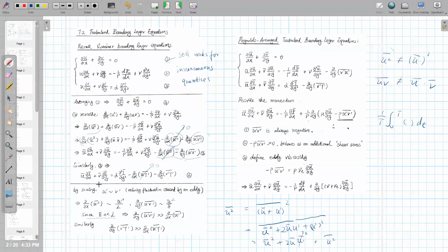And again, the last one, the energy equation. So this term can go, and this will be the final Reynolds average temperature equation in the turbulent boundary layer. Okay, so basically all these 3 will be the so-called Reynolds average turbulent boundary layer equations. All right.